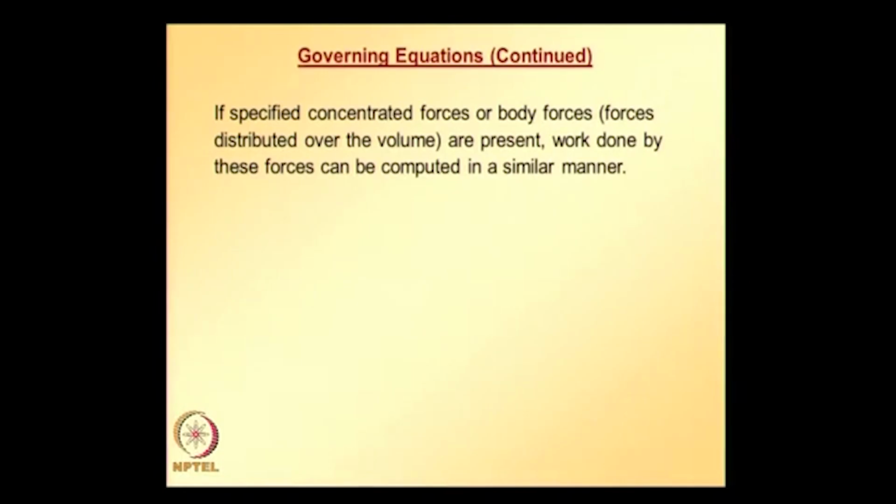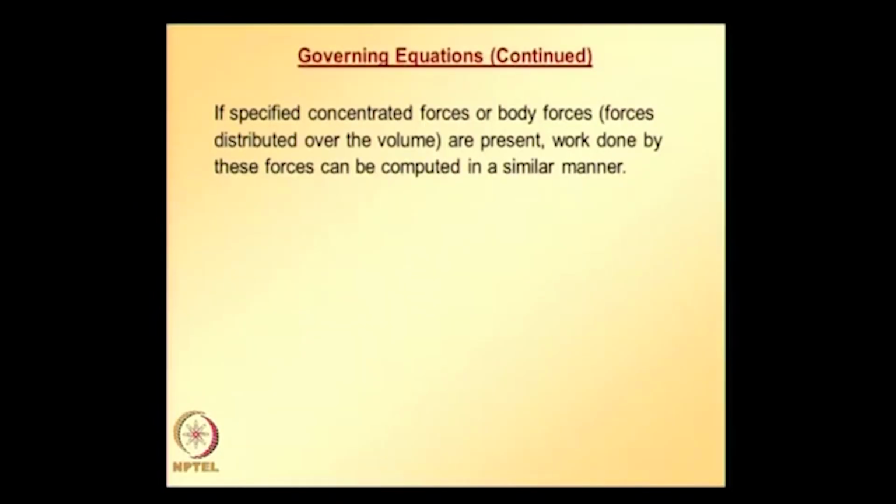So, this is what we have seen in the last class, and also in last class we have seen how to calculate principal stresses once we solve for the displacements and find strains and stresses at all the points that we are interested, and later using the 6 stress components we can calculate principal stresses for subsequent use in the failure criteria. So, with that let us start deriving finite element equations for 8 node hexahedral or brick element.